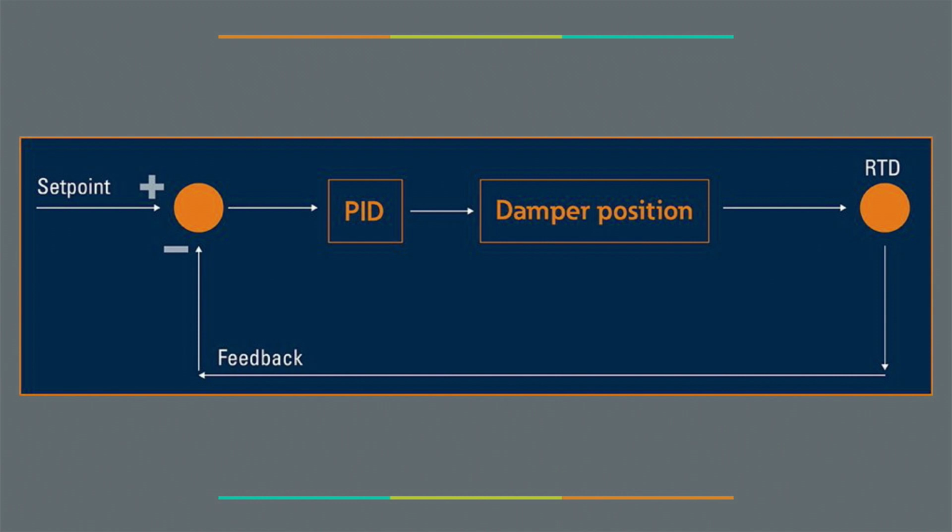As you can see, the RTD, or the resistance temperature detector, feeds back into the PLC along with the given set point, which are then compared and put through a PID block in order to actually implement an output signal, which is used to then control the position of the damper. That damper will then fluctuate in position to allow more or less hot air into the room. Again, this is a great setup that is commonly used, and thank you for the question, Jessica.